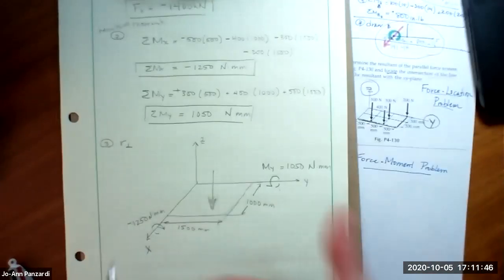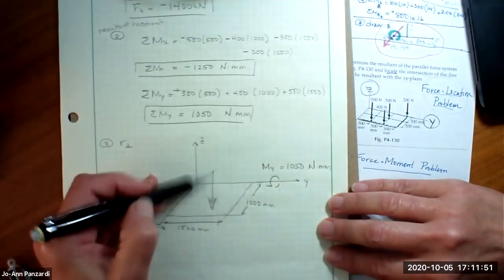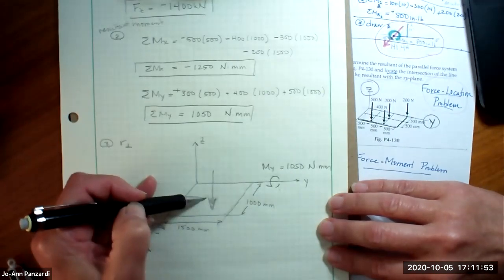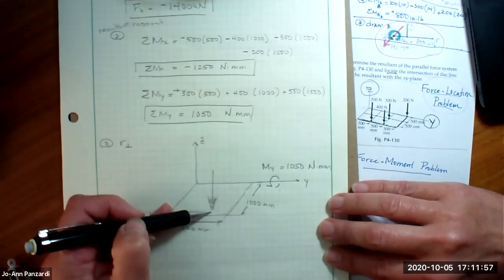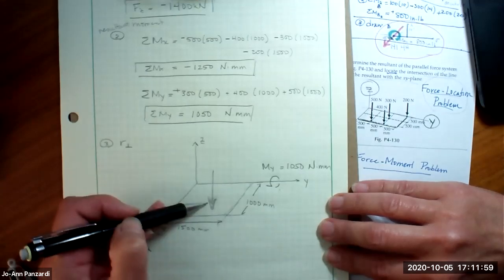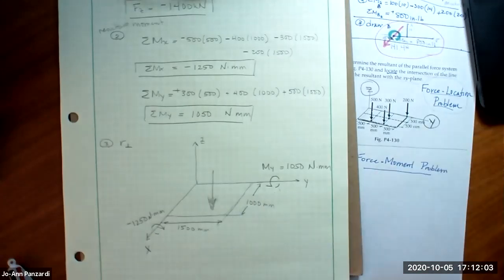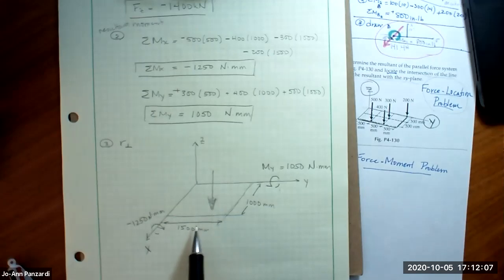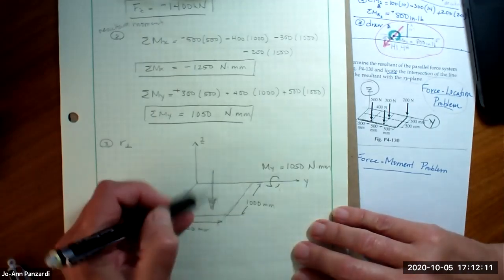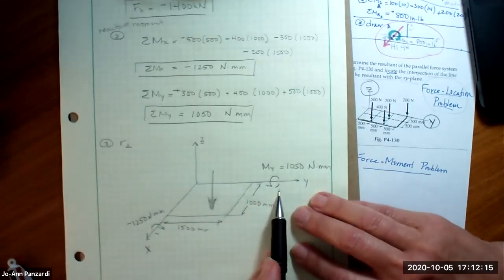So we have a negative moment here. We have a positive moment here. Does this force in this position create this moment? Does a force going down on this plate create a positive moment about y? Yes, it spins it down. And does this force location create a positive? It creates a negative moment. So the force goes down. I have a negative x moment, a positive y moment.